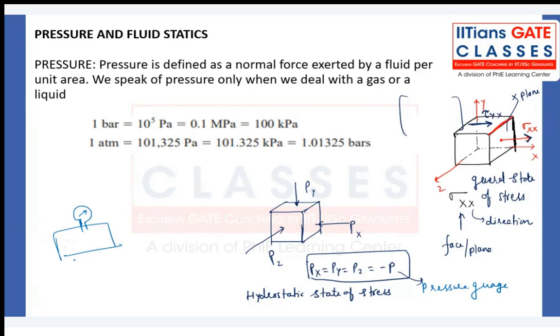It will give the readings of different deformations, and by making a table we can get the values of sigma. What is that? Force divided by area, right? The force will be applied by the universal testing machine directly. There is no such instrument called a stress gauge or something like that, by means of which we can measure the stress. No, we don't have such an instrument directly. We have to perform the experiment, right?